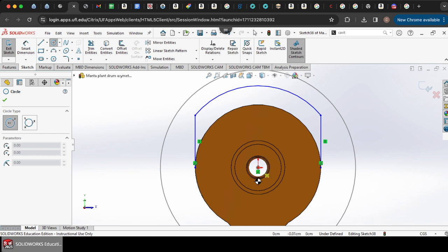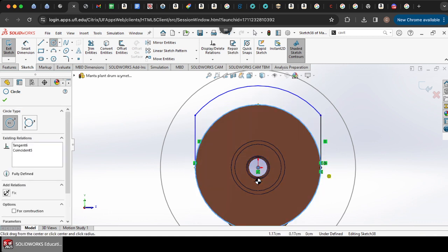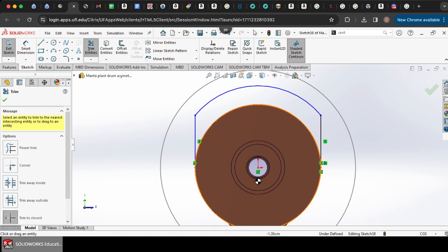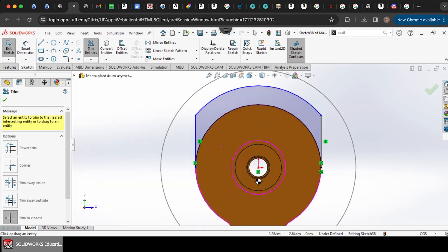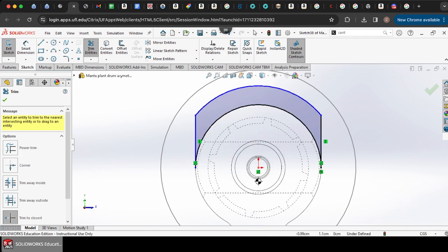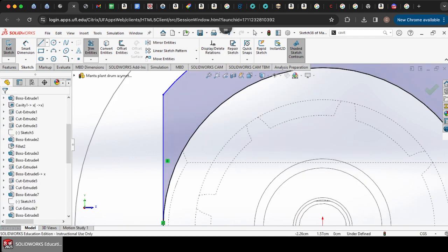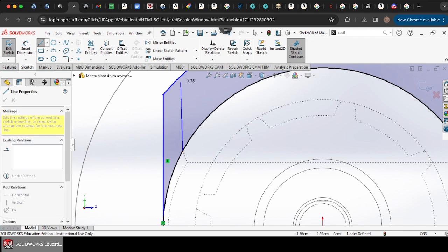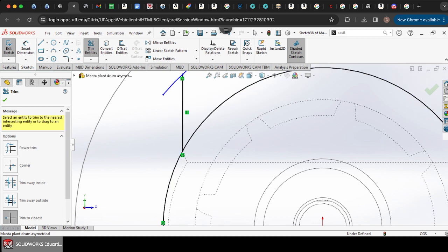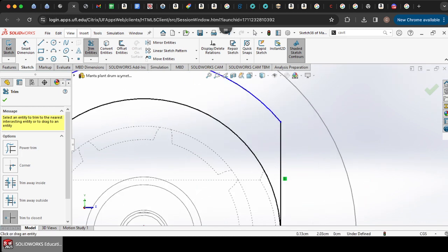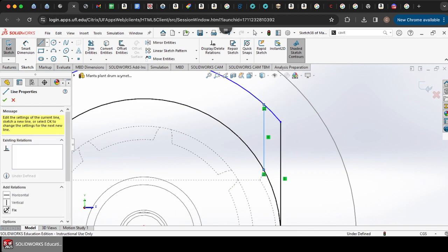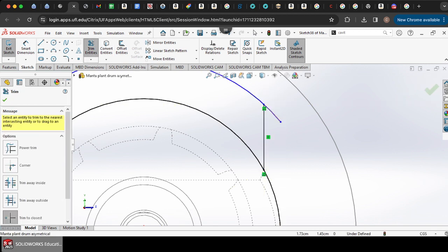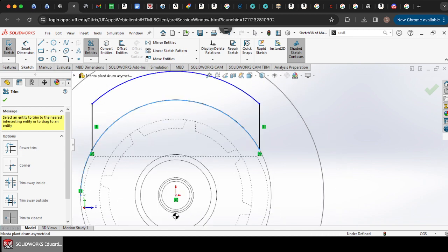So let's go ahead and make this. I'm also realizing just now that if I extrude this, it's probably going to get in the way of some of these. Yeah, it is. Okay, so, yep, important note to keep track of where those things are. Let's do that from here instead, that way we don't mess with that. And because these are symmetrical here, I can just make it right on this other side. Trim away all the stuff we don't need.